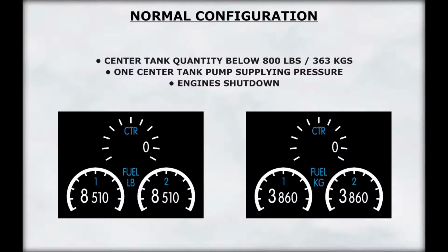The label is removed from view, and the quantity indications return to normal when the center tank quantity drops below 800 pounds, one center tank pump is supplying pressure, or both engines are shut down.